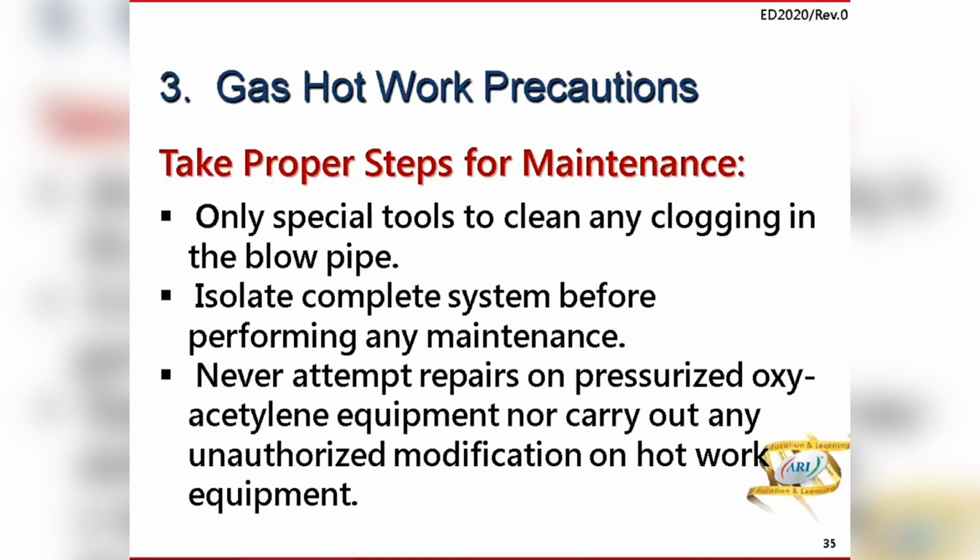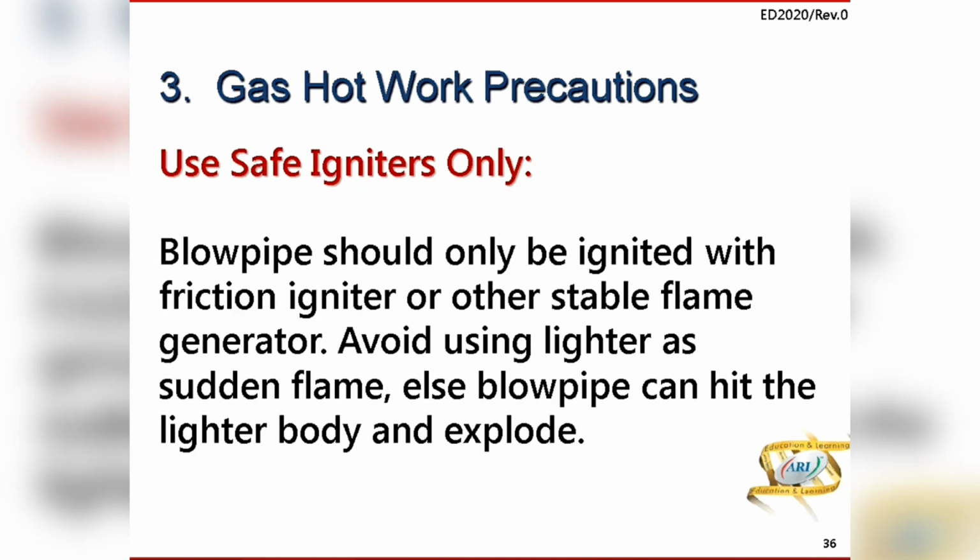Now, for the maintenance part, only special tools to be used for cleaning any clogging in the blowpipe. Isolate complete system prior to performing any maintenance. Never attempt repairs on pressurized oxyacetylene equipment, nor carry out any unauthorized modification on the hot work equipment. So blowpipe should be ignited with friction igniter or stable flame generator. Avoid using lighter as sudden flame, as the blowpipe can hit the lighter body and explode.